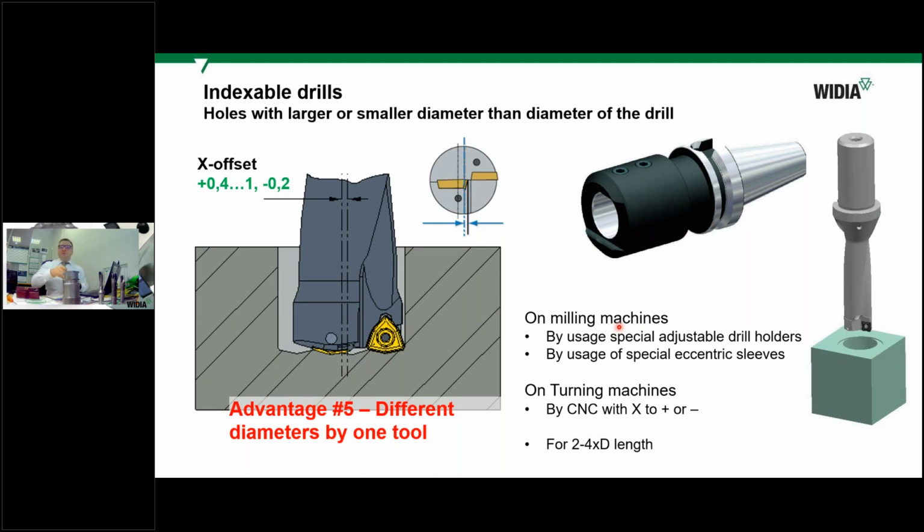And we're not sure what other drills from other producers may do better or maybe worse. So it's like a general recommendation, decrease feed about 2 times. Sometimes a producer recommends to not decrease feed much, only decrease if small problems appear.